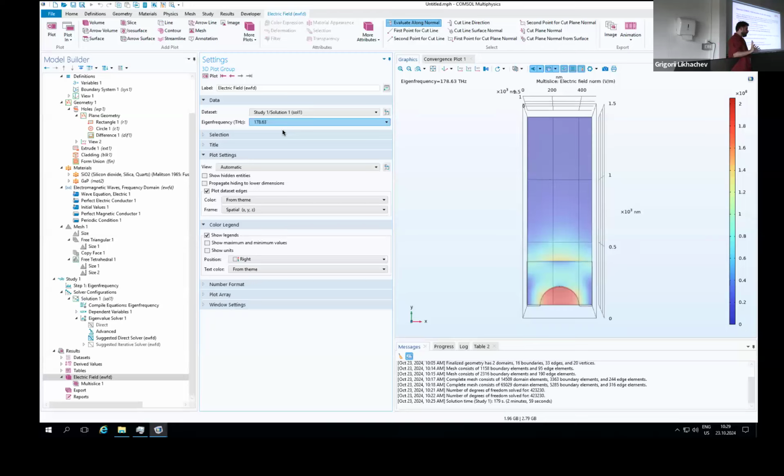You should see, if you simulate it by doing a parametric sweep of the radius, that if the radius gets too large, then basically this alternation of the layers is not good anymore. Now the low refractive index one is too large, and you will see that your band gap is getting smaller again. So there is a sweet spot, and I'll show you my color maps where it shows you how these things change.